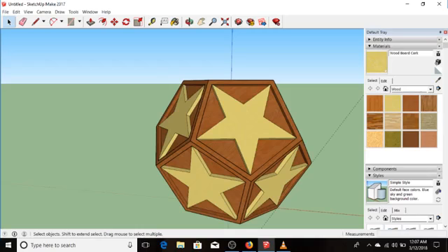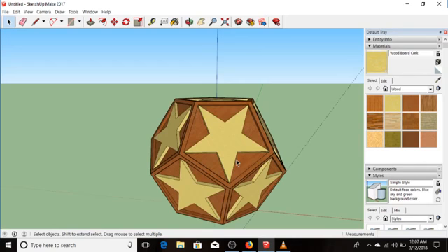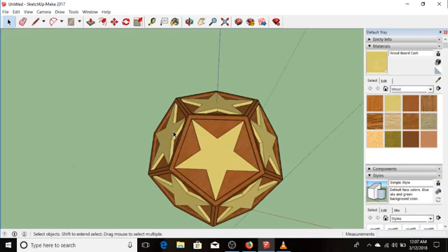I'm going to take it all the way to the actual upload into virtual world. Now we're in SketchUp 2017. Versions of SketchUp higher than 7 have a problem with the DAE file. If I were to export this in DAE in a version of SketchUp higher than 7, it would be broken into pieces. Each one of these star faces would be a separate piece. Each one of these edges here would be a different piece, and there might be a piece that consists of that edge, and that's random garbage.